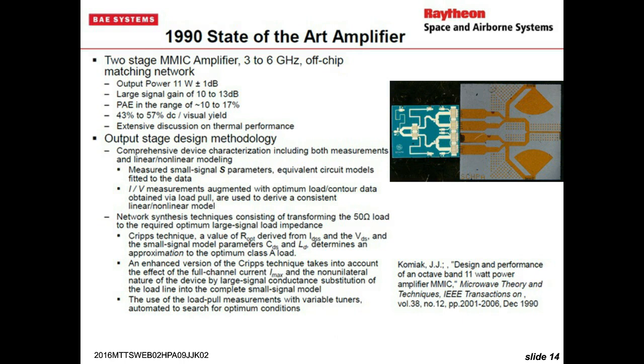I think architecturally it would be better to use a low noise oscillator. First of all, bipolars are much better phase noise wise than field effect transistors. Use something like an HBT, or even indium phosphide if you want to go way up with a fundamental oscillator, and follow it by a power amplifier chip.